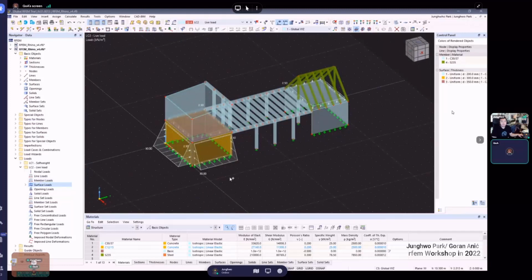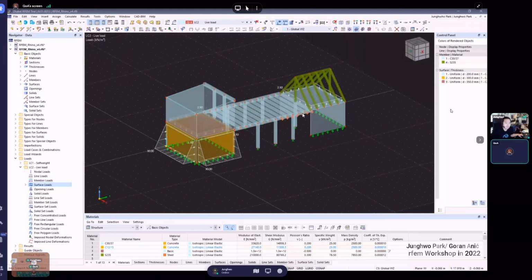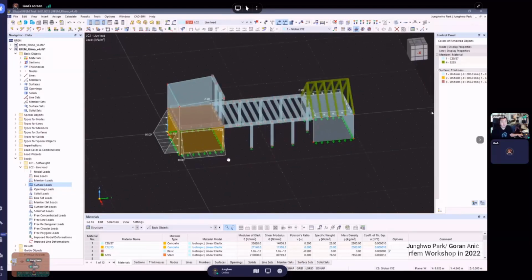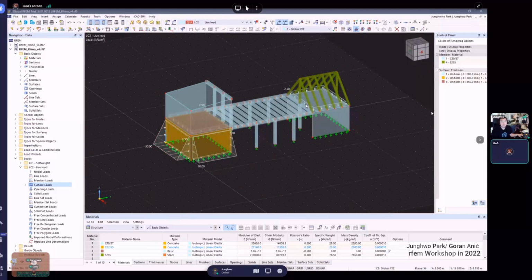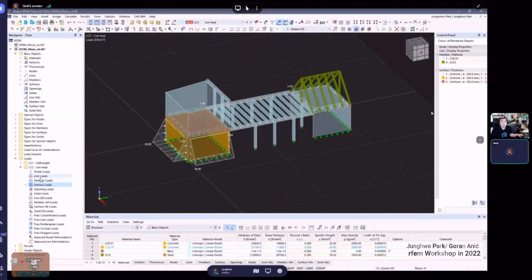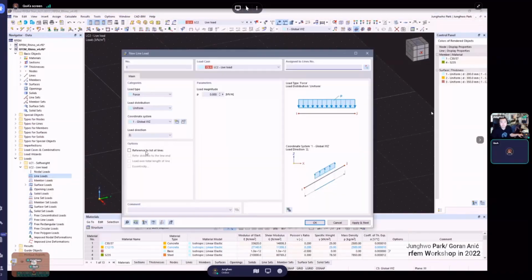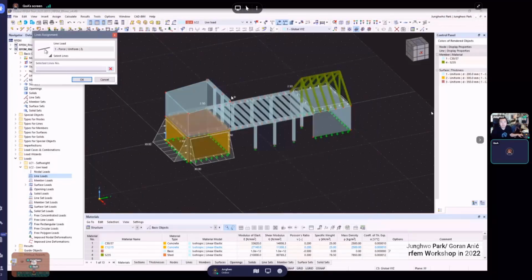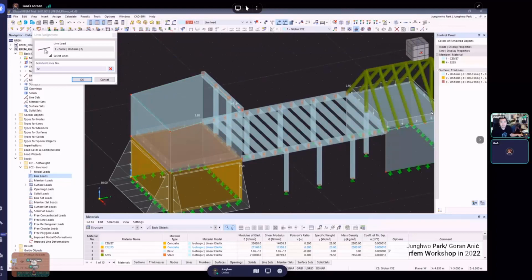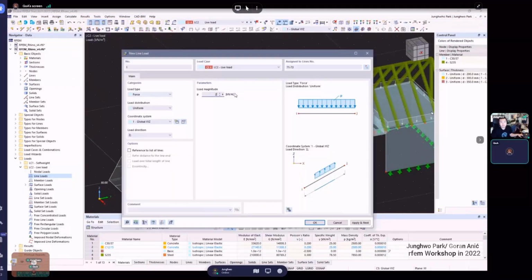That's the most used way, I think, of adding the area loads on surface. Usually we have some of these options. Line loads we already showed. If we want to put some line loads on some elements, we can say, for example, this is on top, there is some maybe signage or something like that, we will have some line load in kilonewton per meter line length.